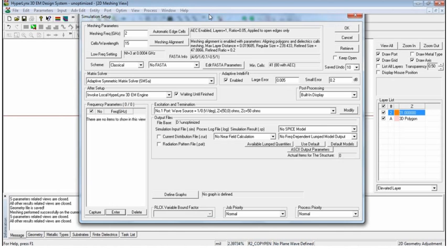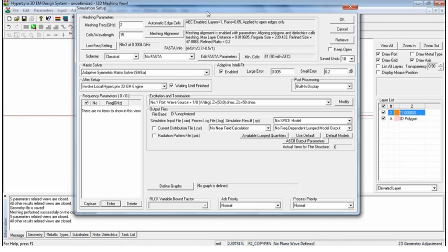So as we know, we have designed this antenna to be operated somewhere close to 1.88 gigahertz because I have done the calculations accordingly so that, if everything goes fine, it should operate close to 1.88 gigahertz. So we need to give a frequency in that particular range only. Like if we have designed an antenna which is operating at 1.88 gigahertz and you are giving a frequency range of say 2 to 4 gigahertz, you are not able to monitor the response of the antenna at that particular frequency. So you should have a rough idea where your antenna is going to operate. So I need to enter the frequencies.